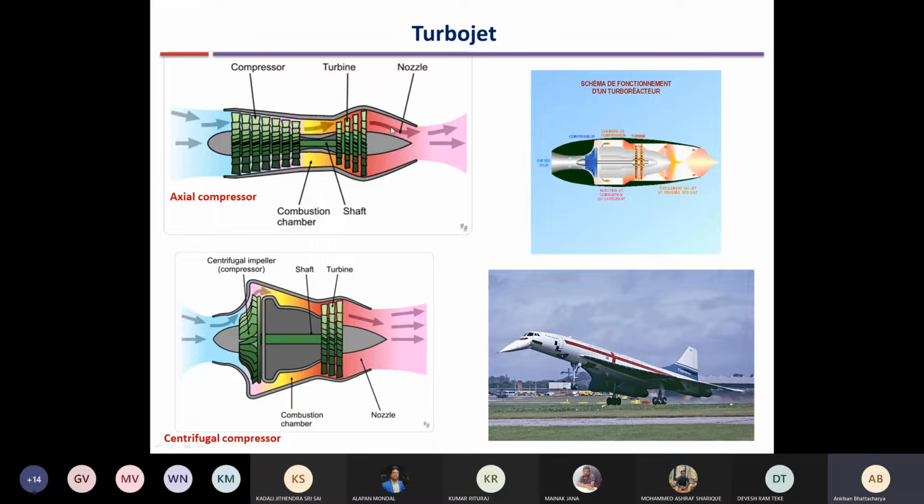By the way, what is the reason of using very high air fuel ratio? Anyway, we'll discuss this later, but I'm just curious whether you know or not. Why is a very large amount of air used? Sir, turbine cooling. Not directly turbine cooling. Means how turbine cooling? Temperature. Sorry? To control the temperature in the combustion chamber.